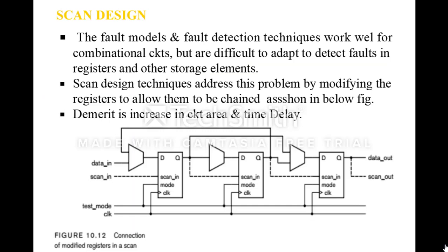The next topic is scan design. This is also a kind of DFT, design for testing. The fault models and fault detection techniques that we discussed so far work well for combinational circuits. But the fault models are difficult to adapt to detect faults in sequential circuits like registers and other storage elements.